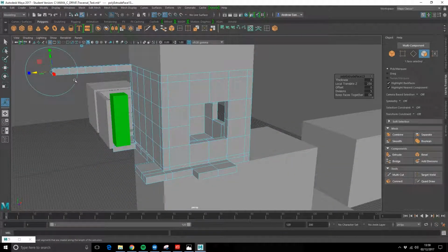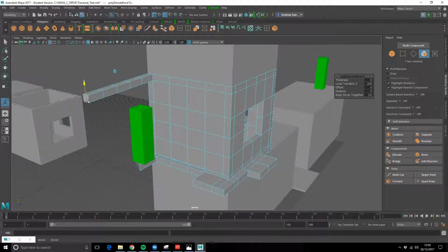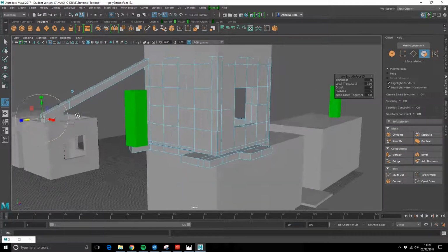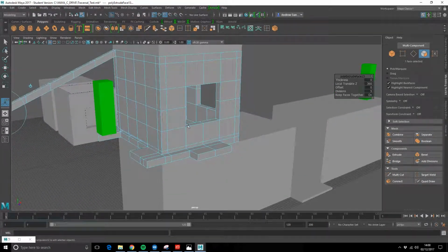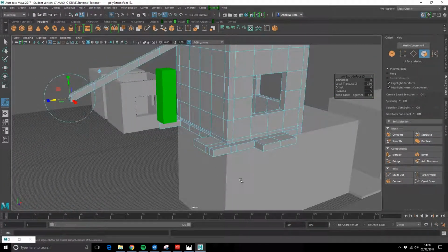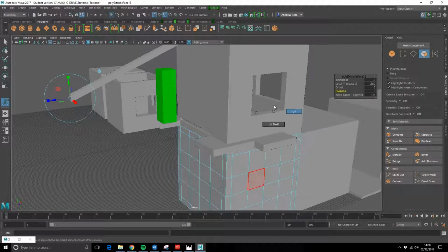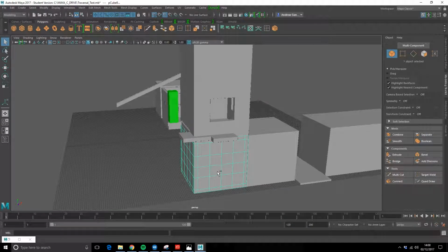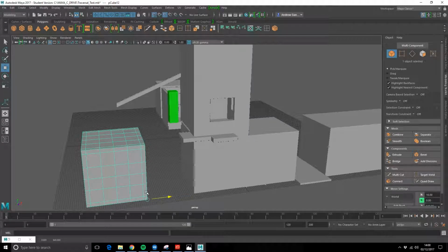And so then I can move this end face, as you can see. So I'm going to basically grab hold of one of these, move it back into object mode or UV mode if you're pressing the wrong button. So Control D that, W, move it. So let's just Control D that, move it. So I'm just getting the width of the road again there, so we're keeping the metrics sensible.